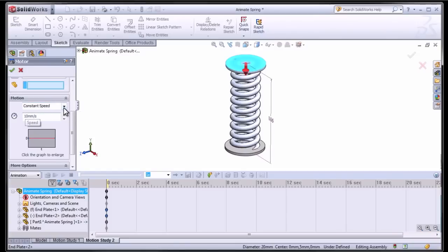So I have the option of constant speed, defined by millimeters per hour. I can do a distance, I can make it oscillating, I can do different segments defined, a data path, or even define an expression. So you can load it in from other files as well, but for here I'm going to use oscillating. My displacement is going to be 40 millimeters. I'm going to go 0.5 on my hertz, and then my phase shift, I'm going to go at 90. So that's the offset from 0.